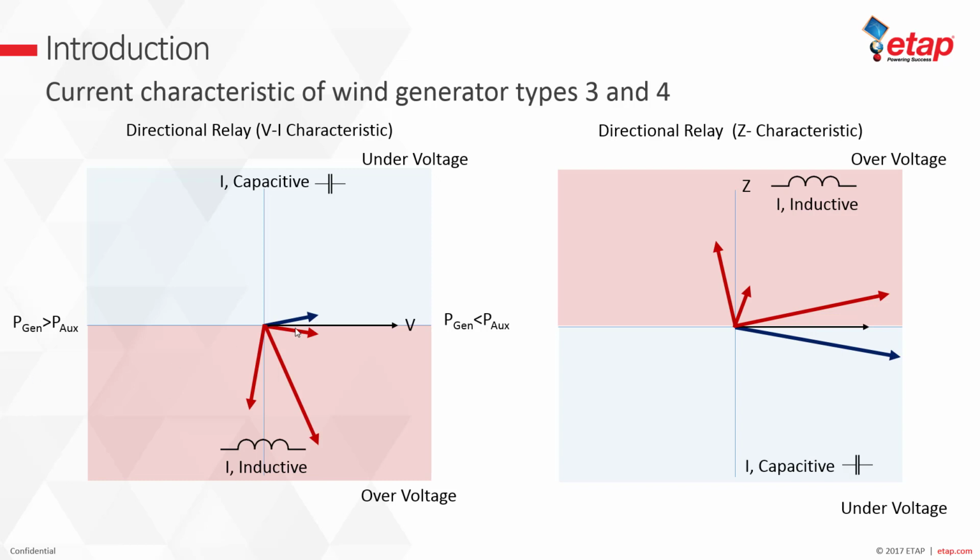So this current here, when translated to impedance, because the current is small, becomes a larger impedance at a few degrees. That basically represents this angle, so it's kind of mirrored with the x-axis. This current becomes this impedance, this current becomes this impedance. And now if I have a current that is capacitive, then it becomes a larger impedance. If it's capacitive here, it's going to be capacitive here, but it's going to go to the fourth quadrant.